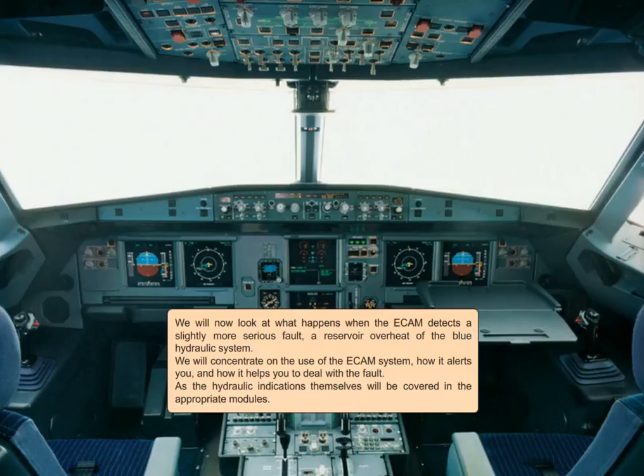We will now look at what happens when the Ecam detects a slightly more serious fault, a reservoir overheat of the blue hydraulic system. We will concentrate on the use of the Ecam system, how it alerts you, and how it helps you to deal with the fault, as the hydraulic indications themselves will be covered in the appropriate modules.